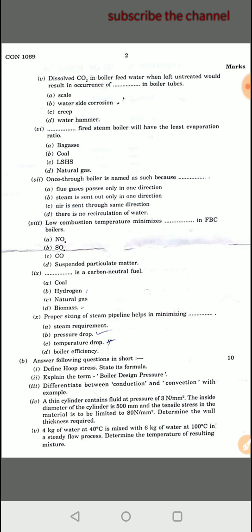10th question. Proper sizing of steam pipeline helps in minimizing blank. A. Steam requirement, B. Pressure drop, C. Temperature drop, and D. Boiler efficiency. We all know that pipeline is related to flow rate or pressure drop. So by proper sizing of steam pipeline, we will minimize pressure drop and get optimum flow rate.